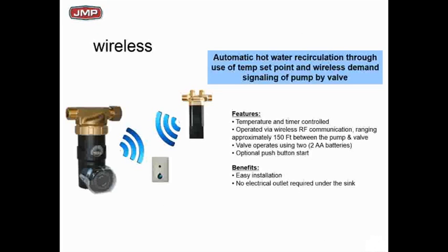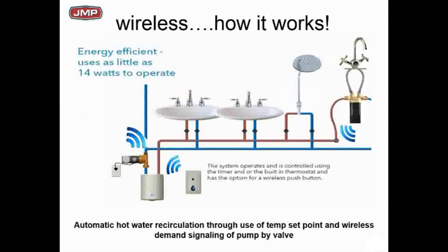In fact, there's a newer version of it that's wireless, where you put the pump at the water heater as shown. Pump at the water heater, and there's a little valve out at that last sink that's wireless that senses the temperature and turns the pump on and off to make sure that you've got hot water. It allows the hot water to go to the cold water side through a little valve, but it's all sensorless, so it works quite well. And look at the wattage, 14 watts. That's nothing more than a night light at my house.